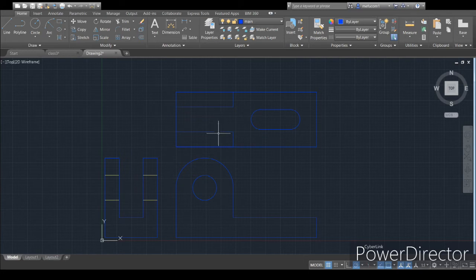Okay, now that we got all that we needed, what we want to do is go to the next portion, which is center lines. I forgot to use my construction, hold on. Going down, okay. Go to construction. What I'm going to do with those is go ahead and make lines going from a view to each section. Escape, enter.